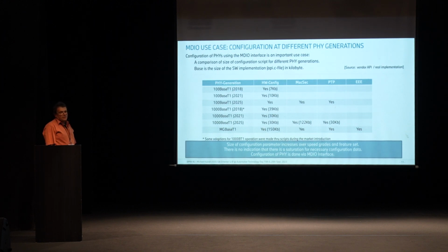In preparation of this speech, I found also another use case which we potentially never experienced so far. MDIO might be the interface to access data we transfer via the OAM channel. So OAM might also become a communication way in a very slow and simple mode to communicate PHY to PHY. And also, MDIO is, in my opinion, then the means of access to this data.